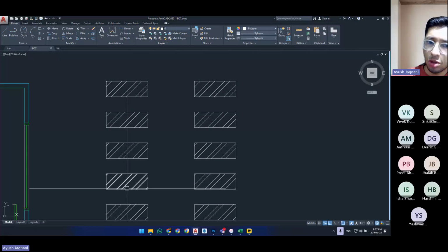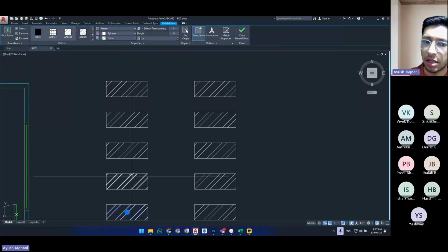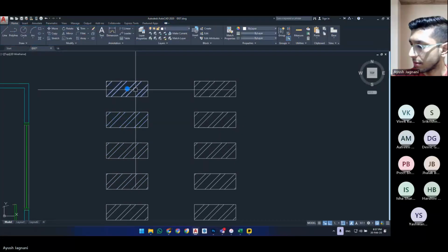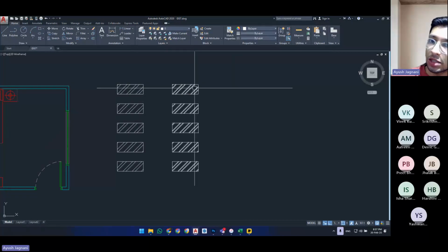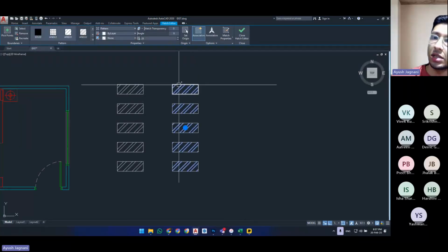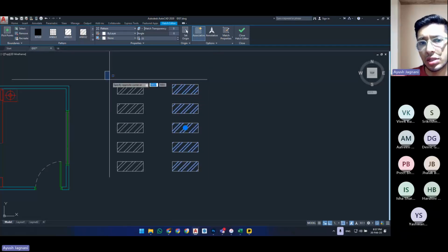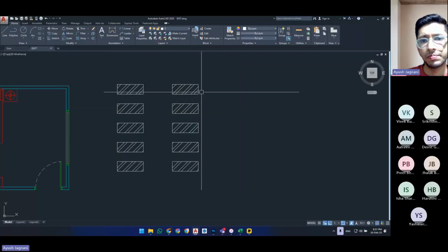In this, separate hatches was turned on. In this, even though all the hatches were created in the same command, they are all treated as individual objects, as you can see. But in this, where the separate hatches was turned off, everything is treated as one same object. For you guys, the most common scenario will be the turned on version. So use that.